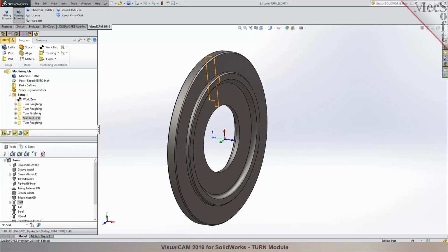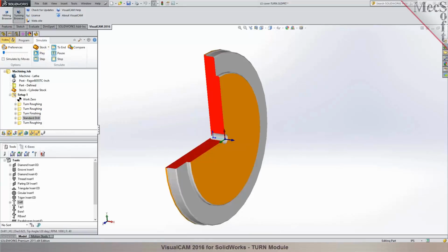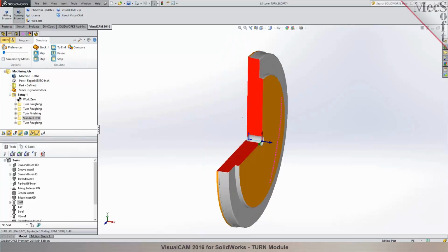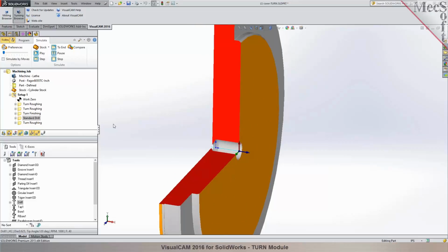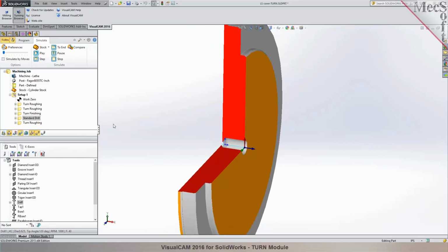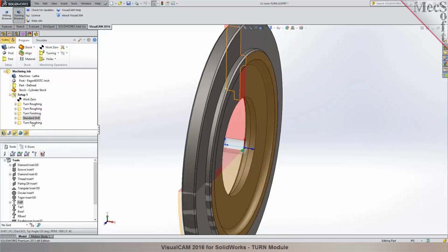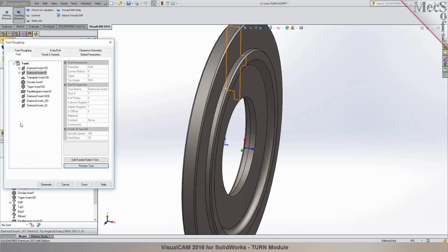Okay, but if you're facing both faces on the CNC lathe, that blank should be centered in, right? The punch should be centered in. Right now we don't have that. Yeah, I see what you're saying. But that's fine, that was just for demonstration, it doesn't matter for that one. When we do it in reality, we have to center it, because it's going to be raw cut from the bandsaw, so we cannot trust the face. We're going to have to machine that first.